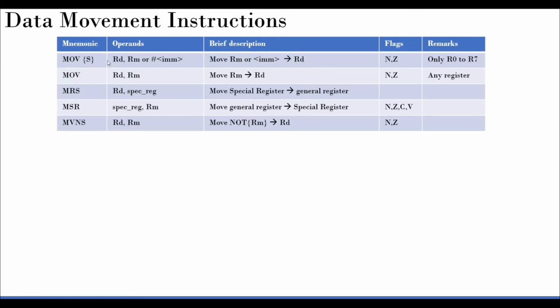You can find that error and of course correct it, but it is good to know that whenever the S suffix is used, and this applies to move, add, wherever, it means that the flags are updated. So when you do MOVS, the flags will get affected. If it is the plain MOV, the flags may not get affected.